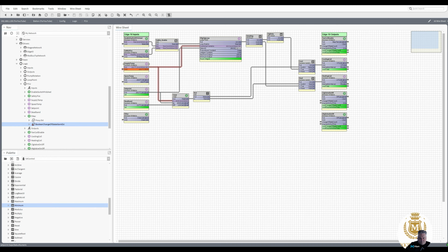That's going the opposite way. We've got a minus on our heating coil, which is fine. Minus is fine. We're not going to do anything, but then we're going to start heating now. So that's now increasing to heat. And we got that 0. So we never have both coils running at the same time. And we have this 2-degree differential on that switch there. So that's it for that one.